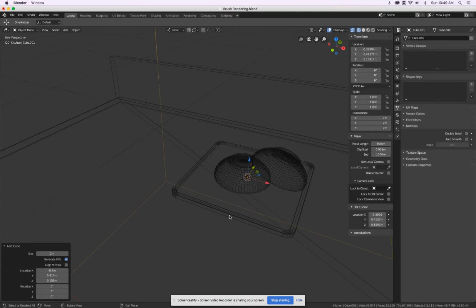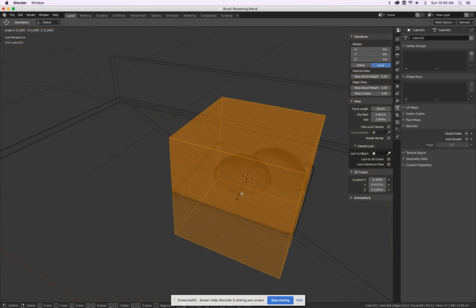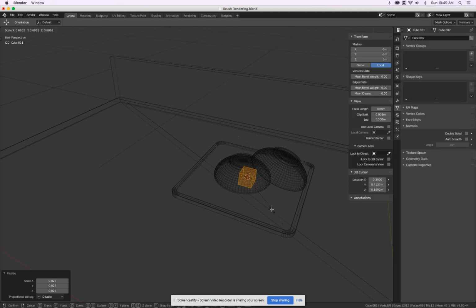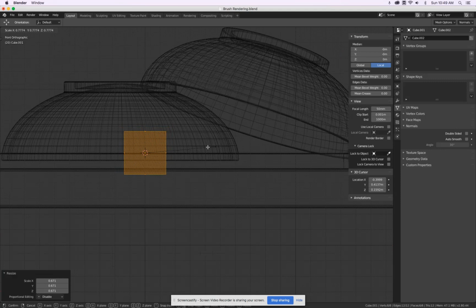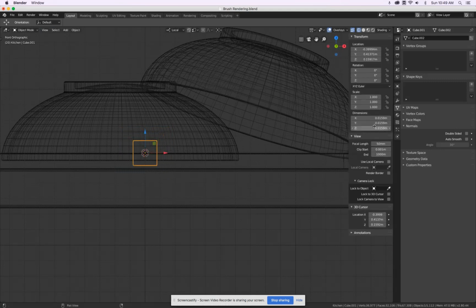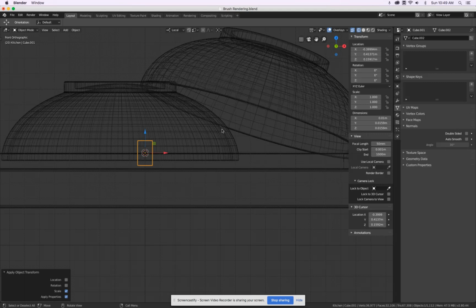And then Shift A in object mode. Again, so I exited the edit mode. Make a cube, press tab to go into edit mode, scale it down. This is really important. Now I do this in edit mode. Then I look from here, scale in object mode. Let's say, yeah, 1 centimeter width. This is fine. And let's apply this. Good.